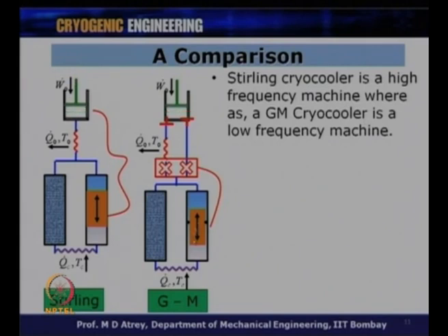All right, because we talked about having this seal. If this seal starts moving at a very high frequency, then this rubbing seal will not function properly, and therefore, the displacer works at a very low frequency of, let us say, 1 to 2 hertz, and that should again be the frequency of the rotary valve. So, the opening and closing frequency of a rotary valve should be the same as that of the GM displacer in a GM cycle cryocooler.